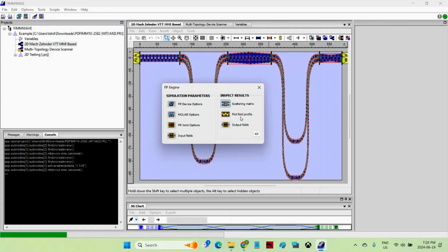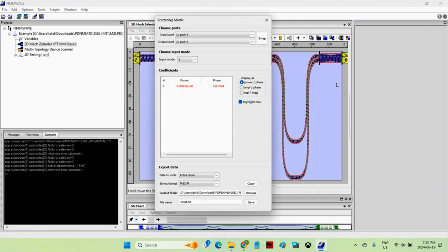And then we should see pretty much the opposite of what we saw previously. Previously we had 90% power in port 3 and 0 in 4, and let's swap it around, and hopefully we see a high transmission into port 4 at this wavelength. So port 1 to port 3, that was 90%, now it's practically 0. Port 1 to port 4, 93%. So at those two wavelengths we get the opposite transmission.